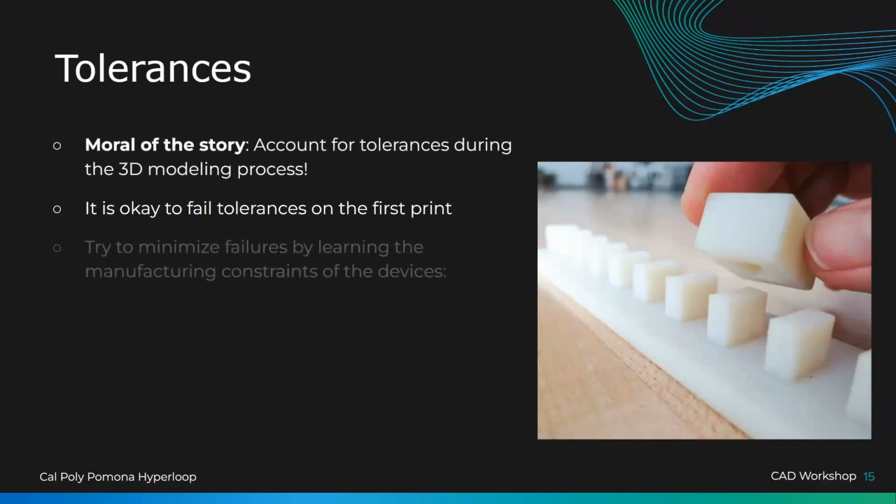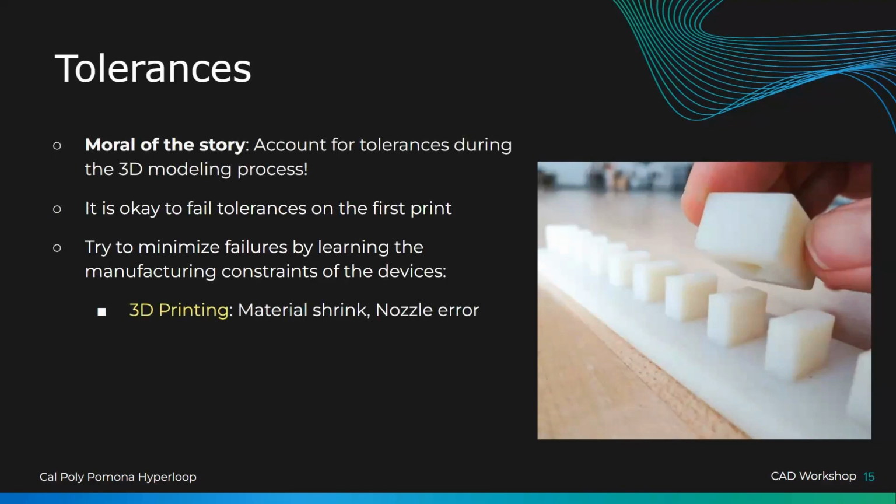Continuing on with tolerances, just account for this during 3D modeling. And it's fine if you don't get it right the first time. That's what these test strips are for, so that you don't screw up a big, important, time-consuming piece over something as simple as tolerances.